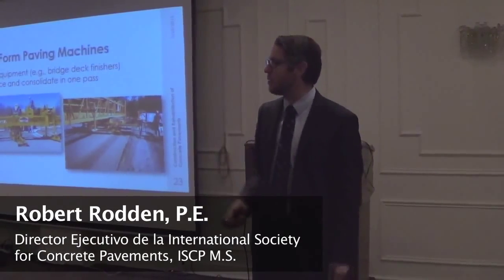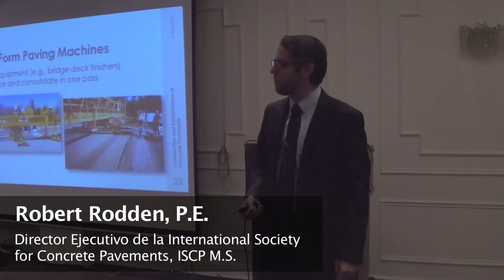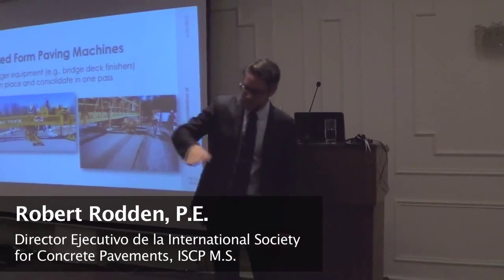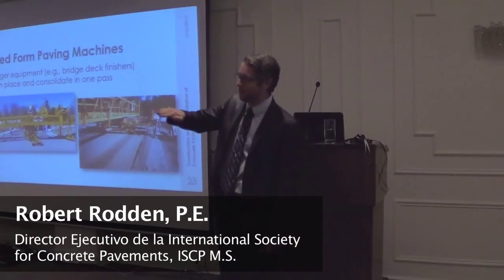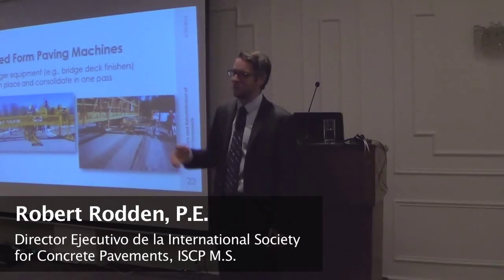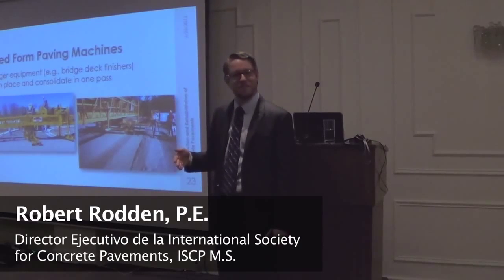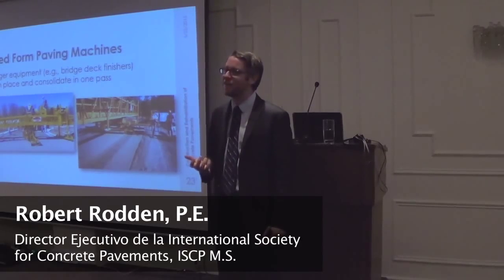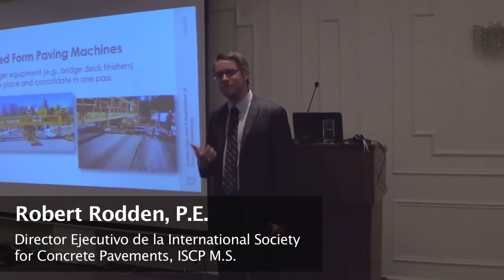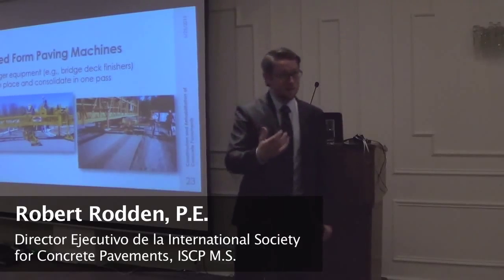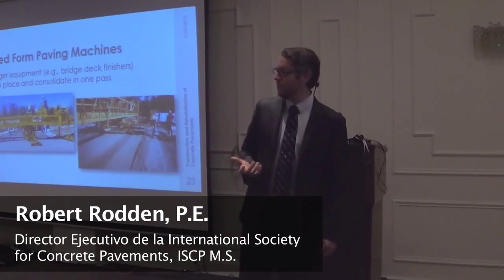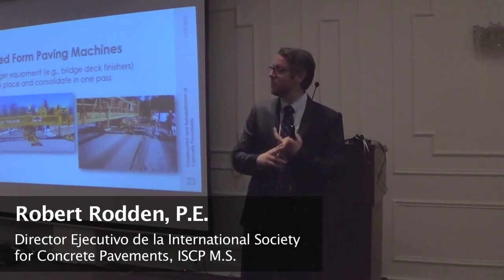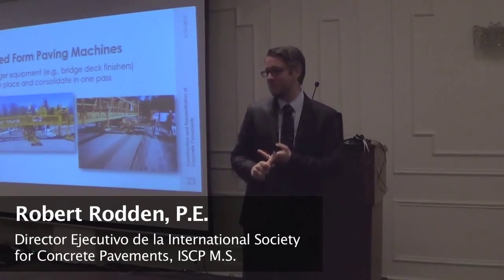Like I think one of the examples I have in South Africa, later, they have a road that they built with a negative curvature so that it serves as a ditch. They had so many problems with erosion in this mountainous area that they decided the traffic is so low, we can afford concrete, we're going to build it with concrete because that's erosion resistant compared to this emulsion asphalt and earth that we otherwise have.